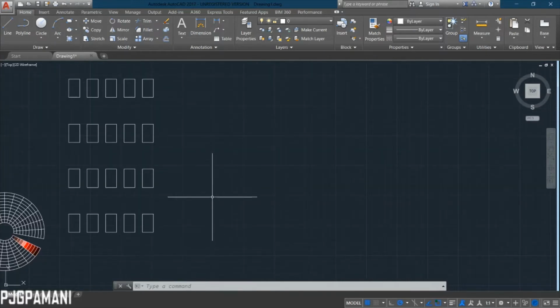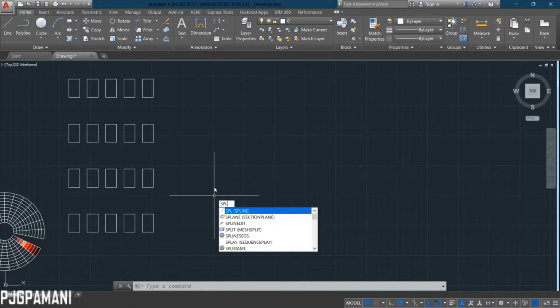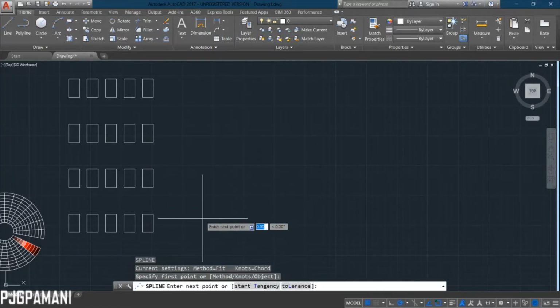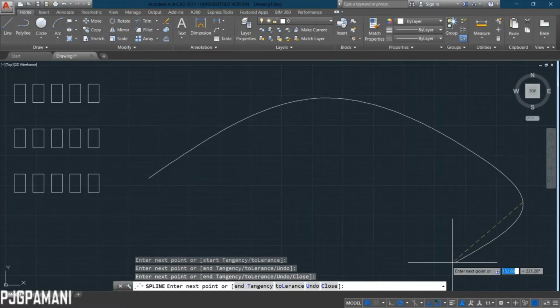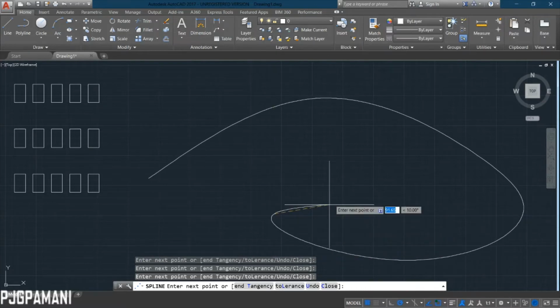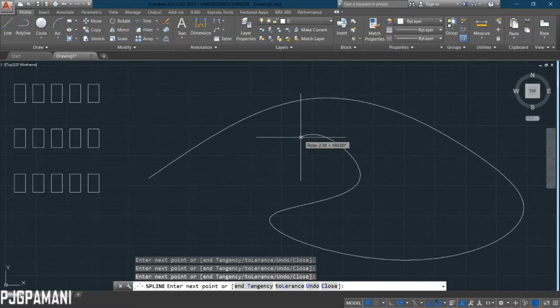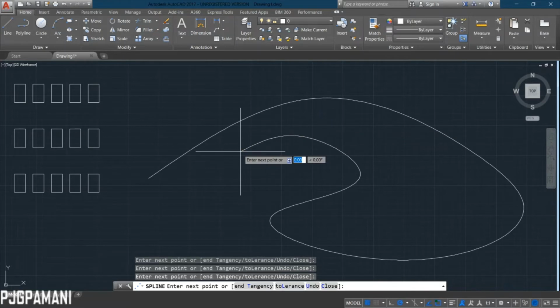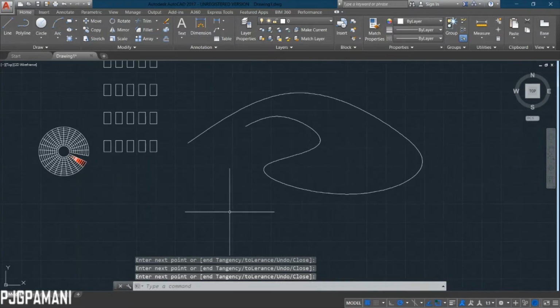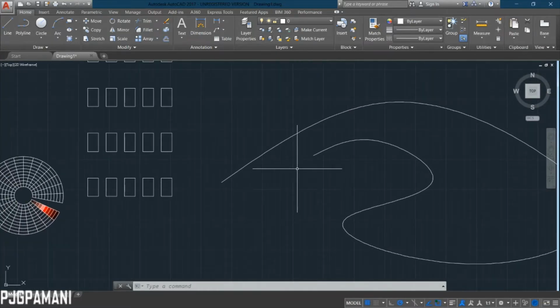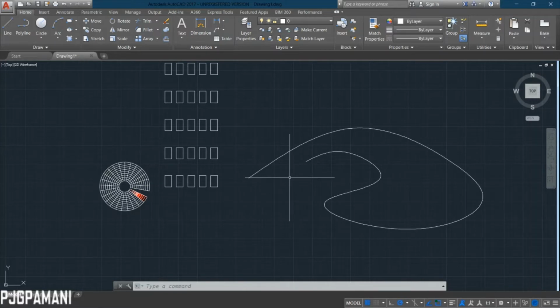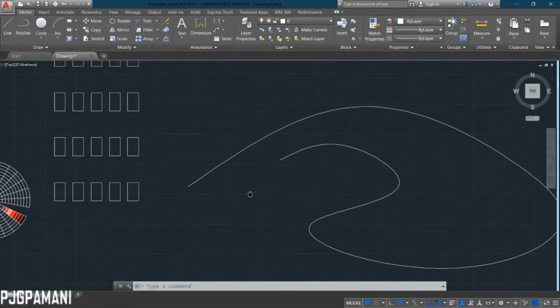With this particular function, let me introduce another type of command, which is your spline. Using spline, you can input a polyline of a specified curve. This is a wonderful command when it comes to plotting a topographic map, connecting points to points, then it will eventually draw its own curve path when it comes to topographic mapping.